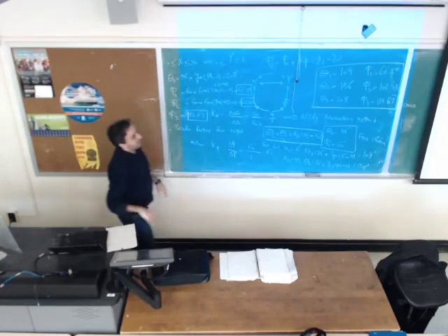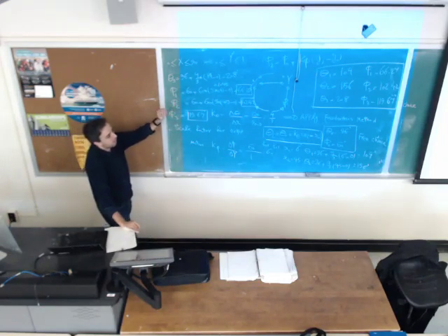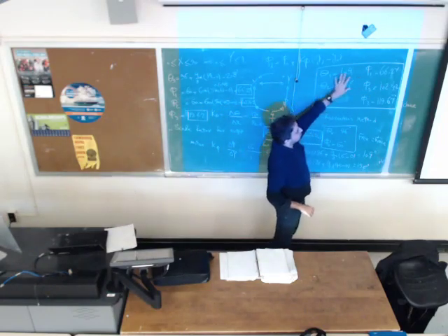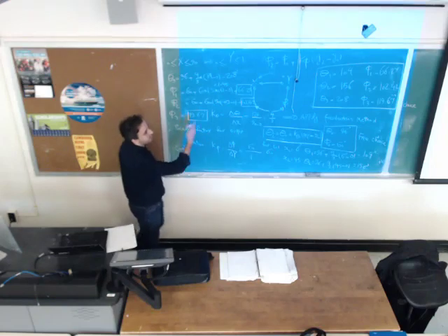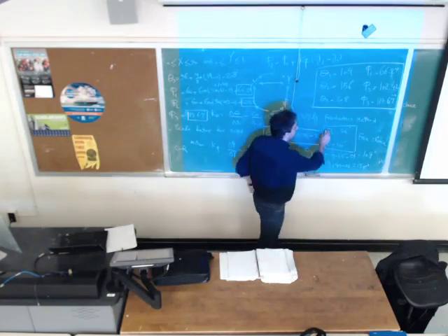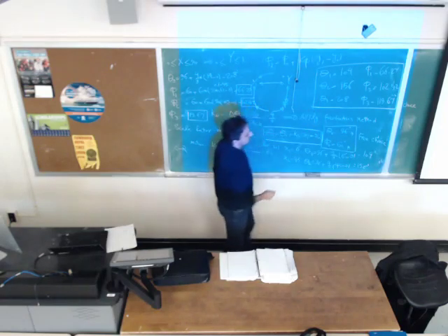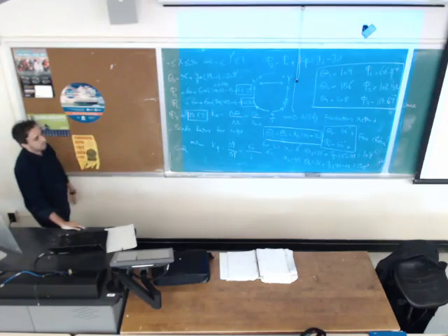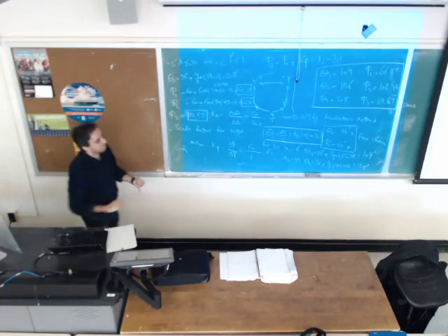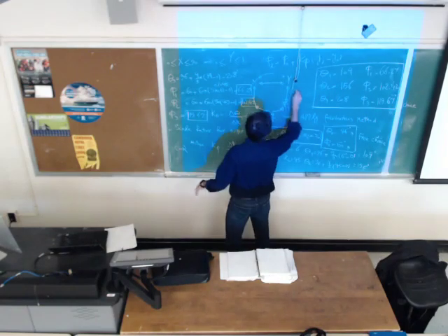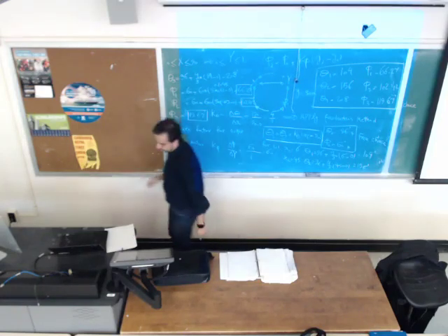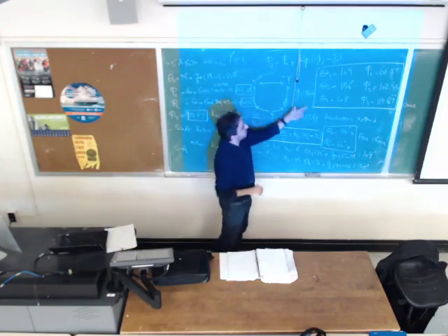In the homework problem, I ask you to do the same problem, just write the code to design the mechanism, but I think I added one criterion: make it crank rocker. So after you find A, B, C, and D, you check for crank rocker. If it isn't crank rocker, change these two. Change one or both to satisfy the criteria. I gave a problem similar to this in one exam, the final exam. I just changed the function from y equals sine of x to something different. It just changes the correlation between y and x, but the approach will be the same.